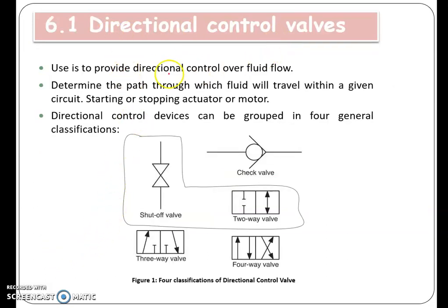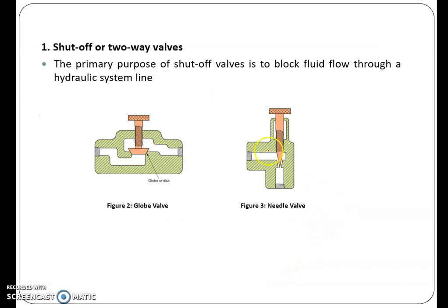Directional control valve is used to provide directional control over the fluid flow. It means kalau awak nak control the direction of the flow, you will use the directional control valve. There are four general classifications: first is the check valve, two-way valve, three-way valve, and four-way valve.